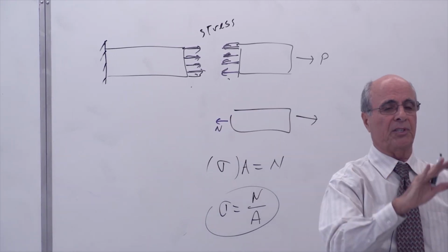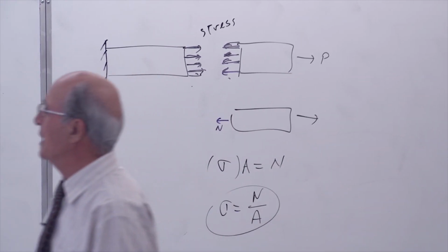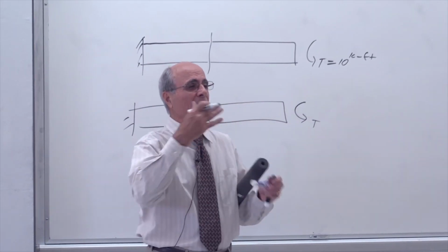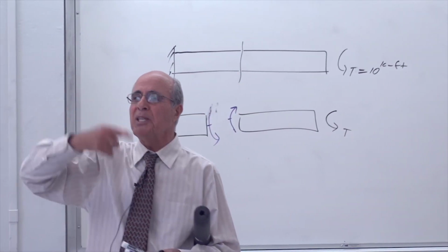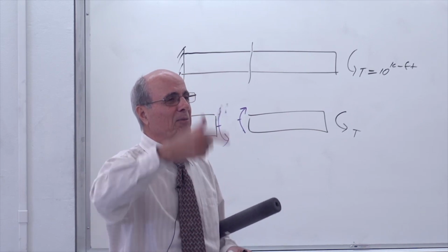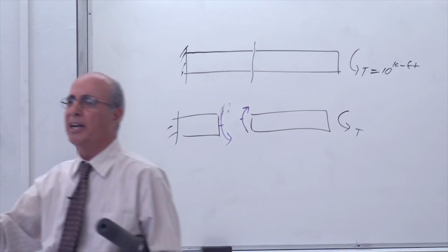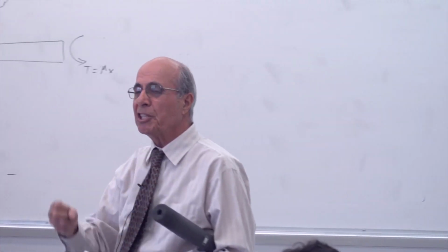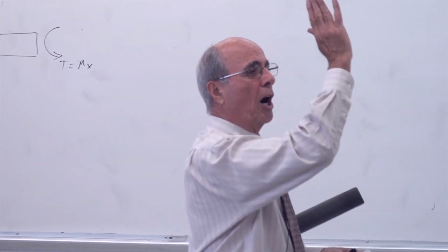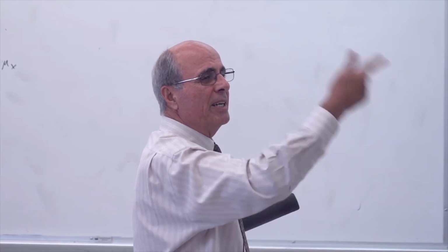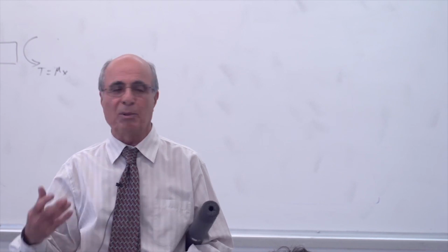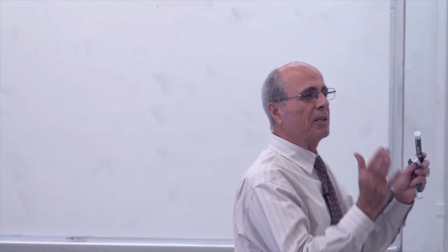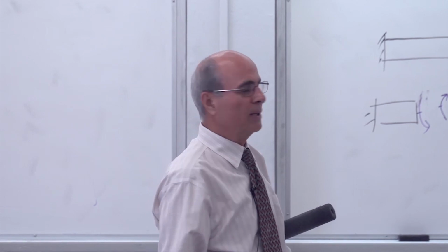Now, this is the point, write it down in your notes. I have to have stress in this cross section. When I add it up, it becomes similar to a torque. Everybody understand? It must be going circularly. This is the key for the entire understanding. So the shear stress in the section is not going up and down. It must be in a circular format, in order to become a torque. Is that correct? Everybody knows the torque. For a torque, you need a couple. Yes or no? We'll see that in a minute.